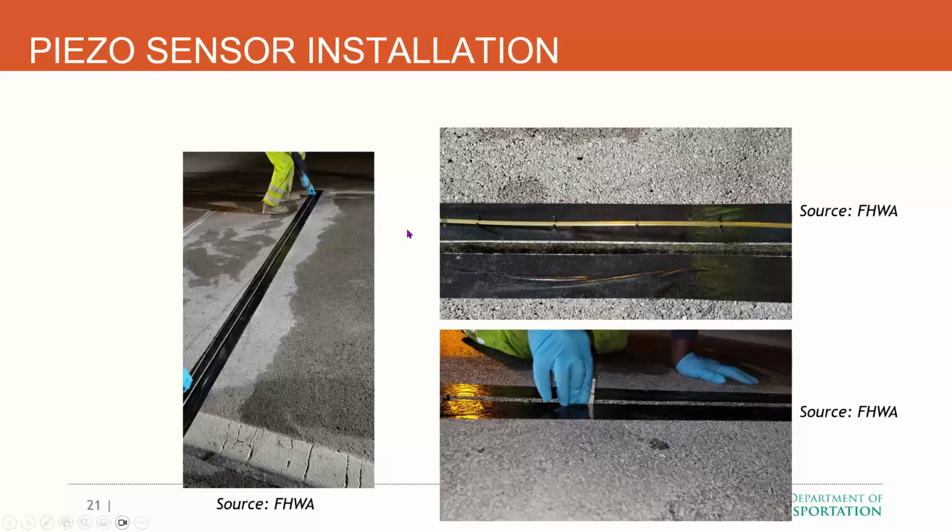So when we're looking at these installs, since we like to install these in new pavement so they last the longest, we like to install these either the same construction season if it's an early pavement project, or we install them the following spring. And I am cognizant of the fact that it drives the public crazy. They think, this brand new pavement was out there, ODOT just finished up, opened this road, and now they're back here closing lanes again and installing these. We understand that, but you can't install this grout in brand spanking new asphalt. You have to wait 60 to 90 days because the oils in the asphalt will also speed up the degradation of that grout, and the grout is the difficult portion.